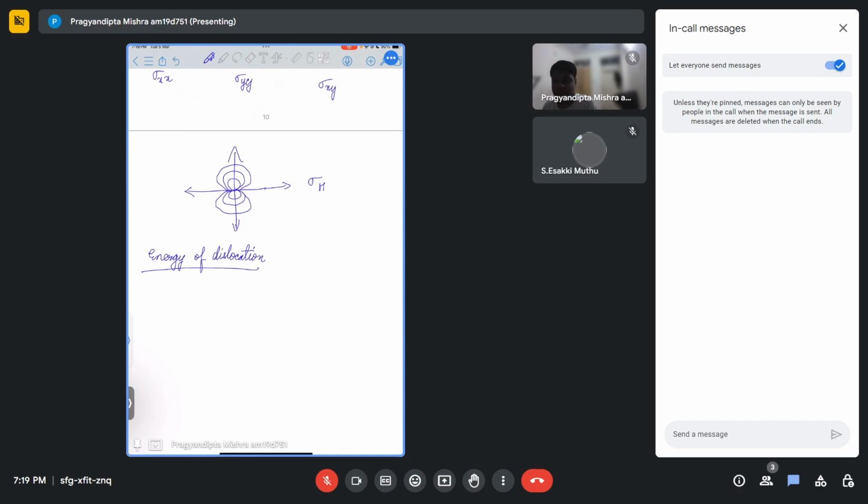Essentially, what we are trying to do is break any dislocation into parts. Let's say this is my dislocation line. Around that line there will be a region where most of the energy of the dislocation core will be concentrated. This will be known as the dislocation core energy. And outside this region, we'll have all the other energies represented as elastic energy for the particular body.